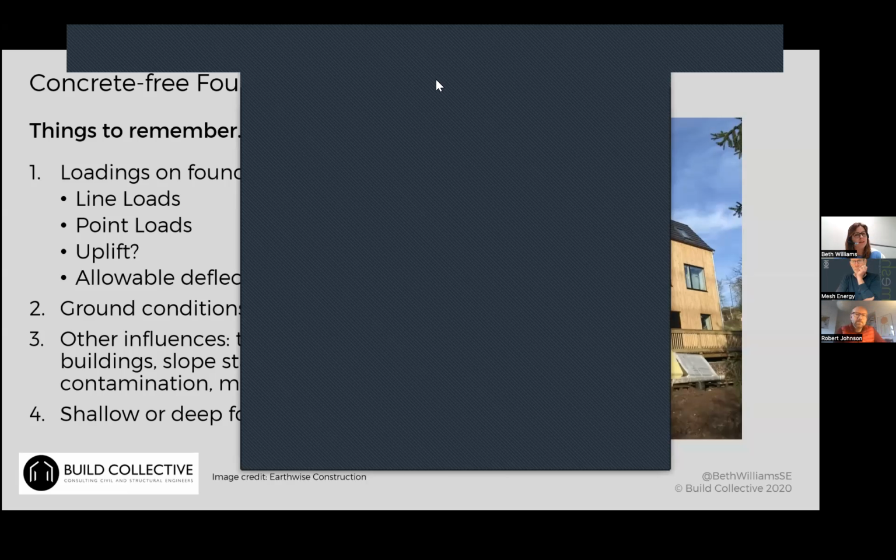Not a standard detail, it would depend a lot on what your above ground structure is. I've seen people encase it in some kind of bituminous painted system, or concrete toppers. There was a company I looked at that were doing a really good precast concrete topper that came ready fitted to your timber pile, but I'm not sure how available that is. That's the thing with timber piles, the availability.